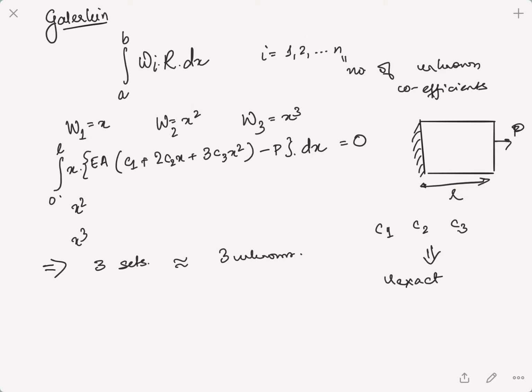But we need to focus on the finite element formulation, and how exactly we are going to do that. With the Galerkin method, it's absolutely important that the weighting functions used in the finite element formulation are the same as the characteristic of an element, which is termed a shape function. Since we have not introduced you to shape functions, I would first like you to do that to understand what shape functions are, and then we will get back to setting up a finite element system of equations with the Galerkin method. So follow the video first on the shape function formulation and come back to the Galerkin formulation.